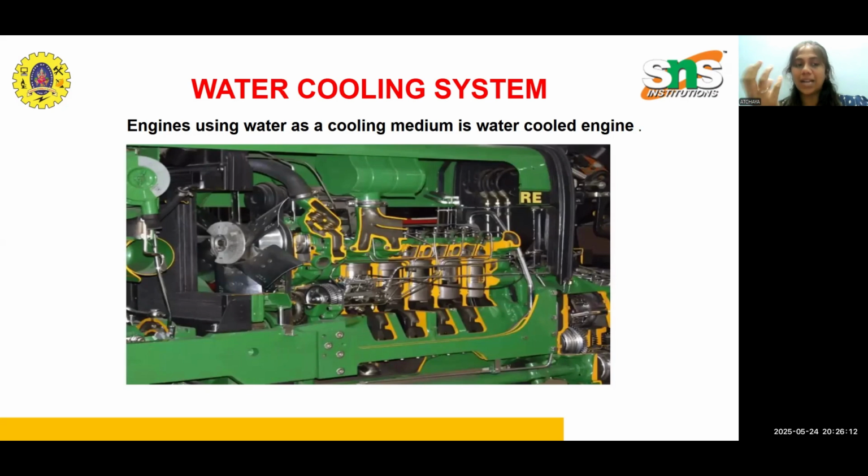Then the batteries in electric tractors, how is the cooling system working? Not water cooling, how the cooling system is working. Batteries operate efficiently in the 20 to 40 degrees Celsius range. Cooling is via metal plates or tubes that come in contact with the cells of the batteries.